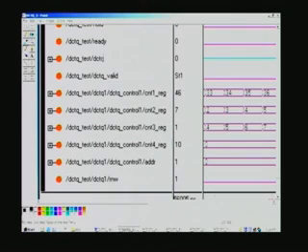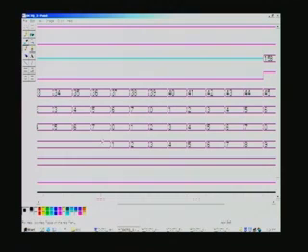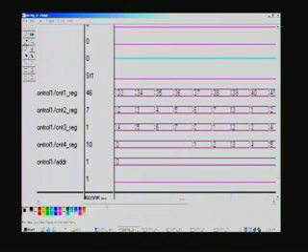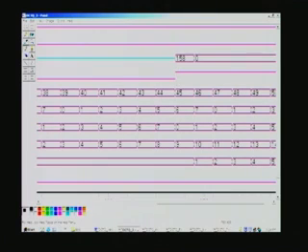We will straight away go to DCTQ and the counter here, further counting has taken place, and now at this stage the last counter, counter 4, is happening at 35, you remember 20, 35 was okay, and then it starts counting. Similarly for DCTQ, address also will be given by the last counter, that will take place only at some 44 or so, you can see 44 right at this point of time, and now you notice that the very first DCTQ block has come only after the 45 clock cycles, so right from the start.